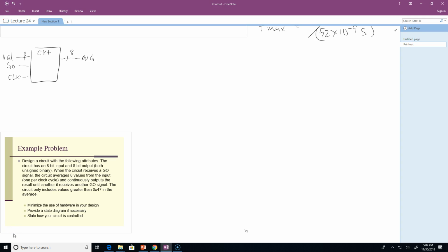The problem is clever in that I'm adding 8 values, and to take the average, of course, I divide by 8, which is a really handy number because I have a device called a shift register that does a great job of dividing by 8. Essentially, what I'm going to do is shift it right. Okay, shift it right 3 times. So that's my divide by 8.